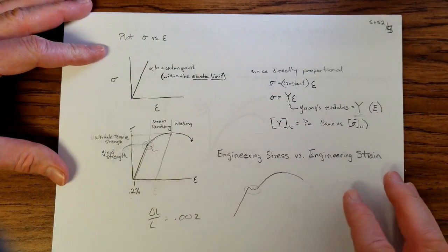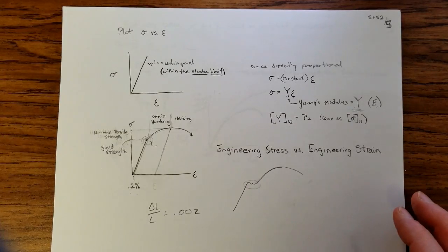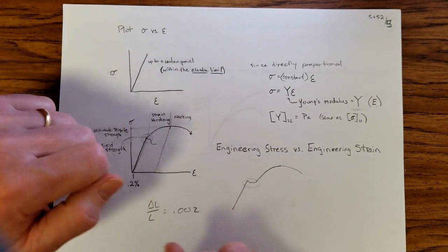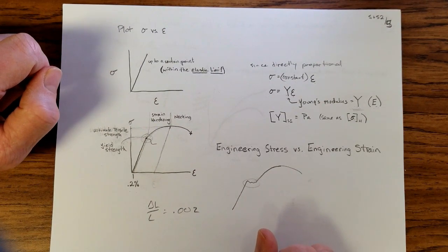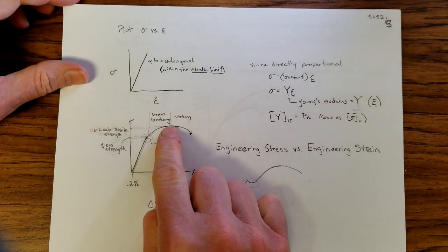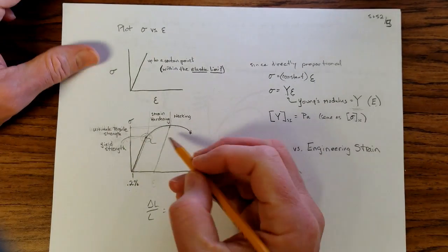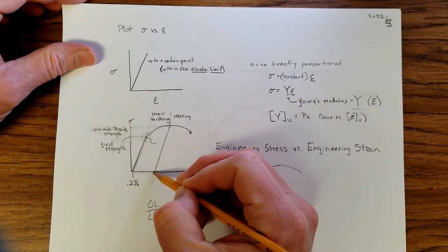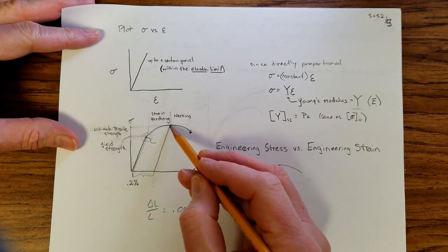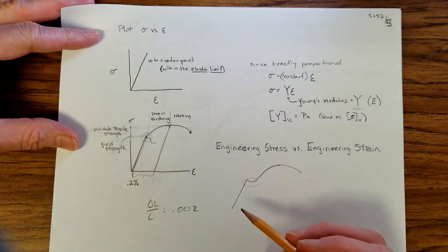That happens at this point. Now, there are times in which it is at an advantage to be able to actually do that. If I take a rod that I know can stretch farther, I can purposefully stretch it farther to put it at this point. Now, when I let go, it's going to come down like that. I'm going to have some permanent strain added to it, but it takes a lot longer before it will deform.